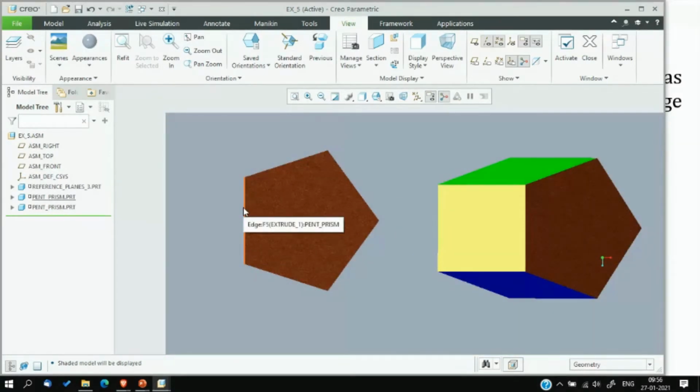Why is it so? Because when we are rotating it, it has to rest on this corner, the opposite corner. In order to make it rest on its opposite corner, we have to place it on one of the end points in the initial top view. Otherwise, if you rotate it, it won't be standing on that particular corner. So this particular point is important.